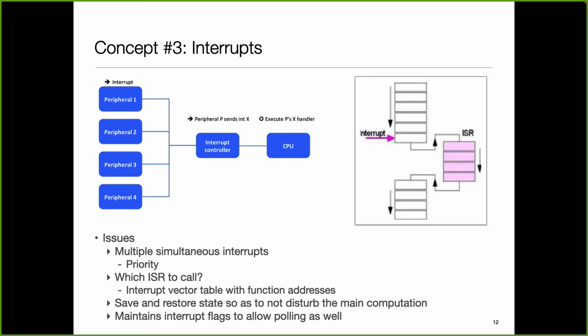So there are things that you can't do inside an interrupt handler, and therefore usually when you write a function which is meant to be an interrupt handler, you have to designate it as such. In some cases, that's how it's done. In other cases, yes, you can write an interrupt handler, but if you do something illegitimate, super bad things will happen. So with interrupt handlers, one has to be careful. Also, when an interrupt happens, then in most cases you will not have nested interrupts, because an interrupt inside an interrupt can be pretty tricky to handle.